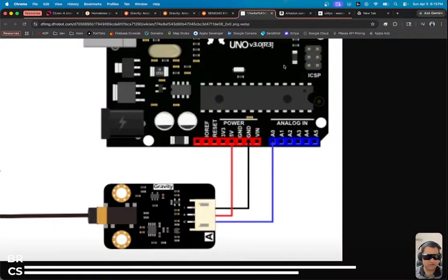Unless I just plug in the entire board to the breadboard, but then I lose a lot. So VIN and ground are easily labeled, but is 3 volt fine? No, it wants specifically 5 volt. Do I have 5 volt on the ESP32? I hope so.